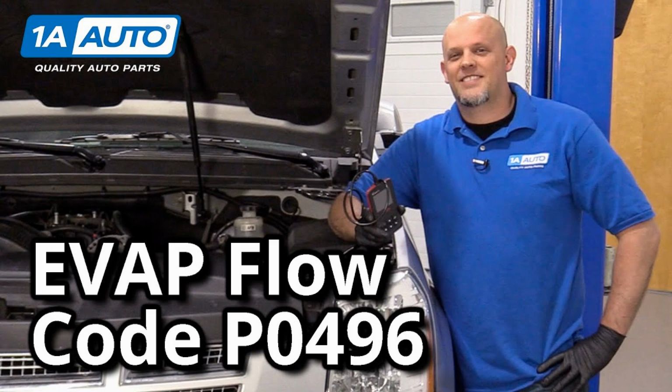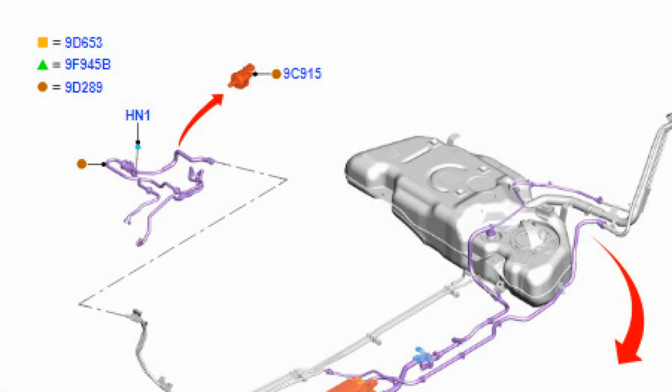Related codes. The P0496 code is often associated with other codes related to the evaporative emission control system, EVAP, and the fuel system. Associated codes may vary according to vehicle make and model. Some of the codes commonly associated with P0496 include P0440, evaporative emission control system malfunction, large leak. This code indicates that there is a significant leak in the EVAP system.